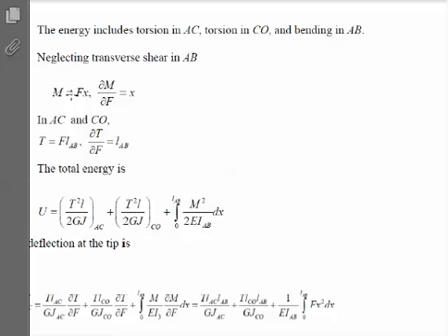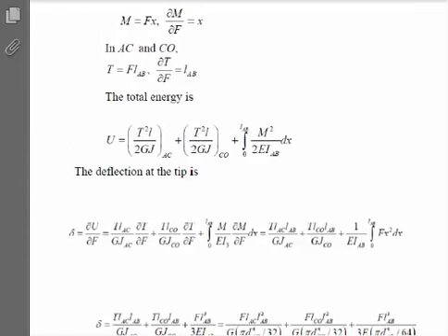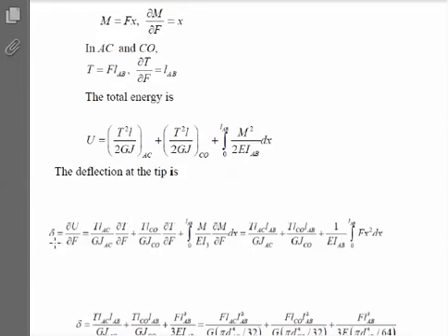The moment squared is F times X. And we're actually not showing this being done as moment times partial. It looks like we're going to actually take the partial of the total energy. Okay, and let's just see where this thing goes. And so our deflection is the partial of this total energy right here with respect to F.